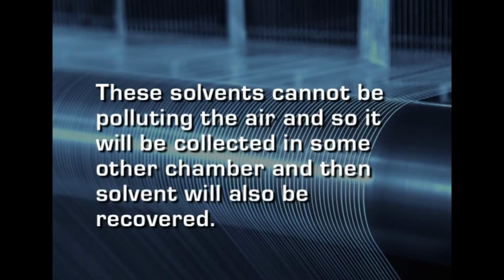In this process, actually 10% of the solvent may be lost or may be present in the fiber itself. But it is considered to be a costly process, because whatever solvents are being used here are all very costly and maybe inflammable also, and sometimes maybe toxic also. So, these solvents cannot be polluting the air, and so they will be collected in some other chamber, and then the solvent will also be recovered and used again for the manufacture of these materials.